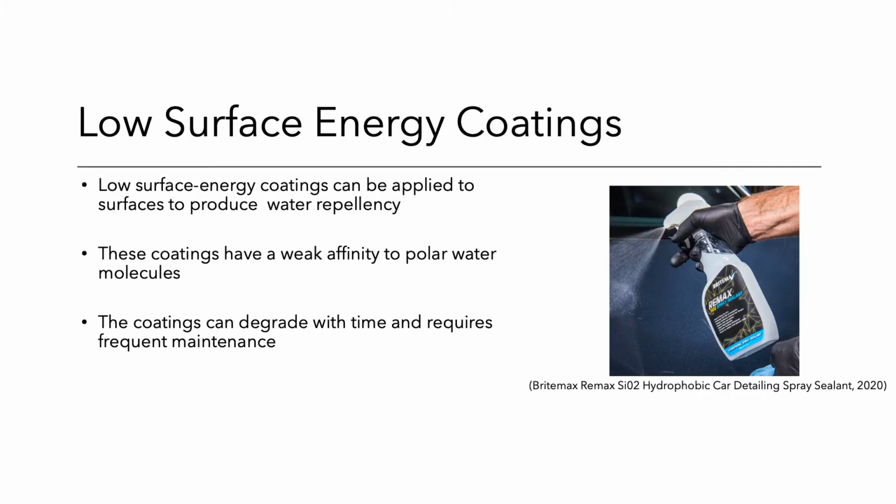In order for dropwise condensation to occur, the surface must have a low degree of wettability. This is characterized by a high contact angle in the range of 90 to 180 degrees at the interface between the solid surface and the forming liquid. Hydrophobic surfaces have been fabricated by applying a low surface energy coating. Highly polar molecules such as water have a low affinity to these surfaces and are unable to form strong bonds to the structure. However, these coatings degrade with time, causing the liquid repellent ability of the surface to diminish.